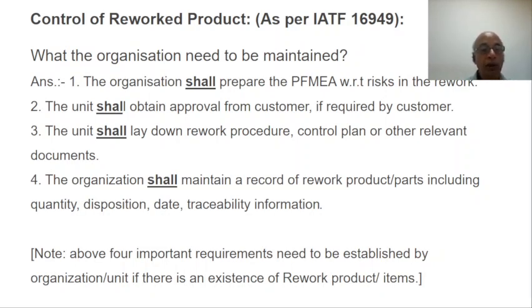The unit shall lay down a rework procedure, control plan or other relevant document. The organization shall maintain a record of reworked product parts including quantity, disposition, date and traceability information. So dear friend, these above 4 requirements are required to be established by the organization, by the supplier, if there is an existence of rework product or items.